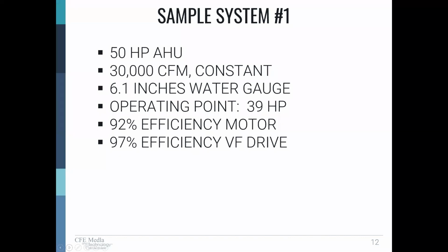At this operating point, for this particular fan, it requires 6.1 inches of static water gauge. The motor would be operating at 92% efficient.